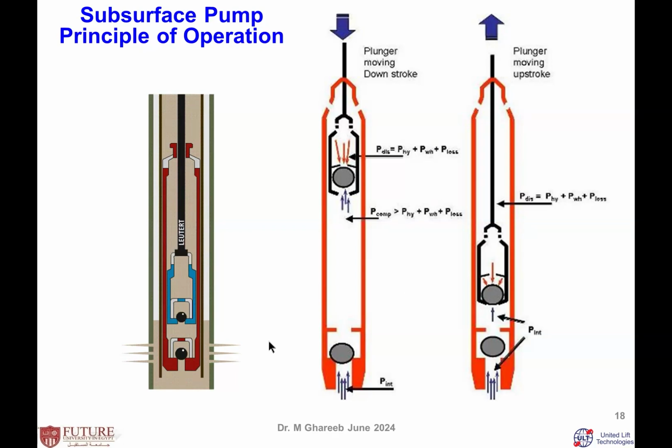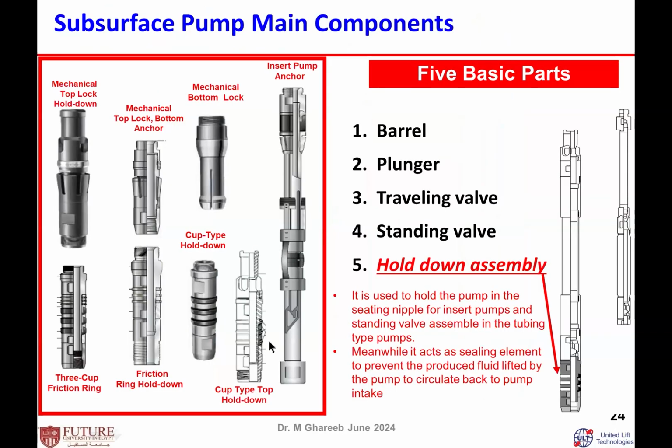Just to make sure you understand how the pump is set inside the tubing, it depends on the depth of the pump, the type of fluids, and the downhole conditions: if I have sand, or hot, full fluid, and so on. There is a variety of bottom-of-the-pump assemblies that can be connected to the bottom of the pump in order to set the pump at any setting nipple or at any place downhole in the well.